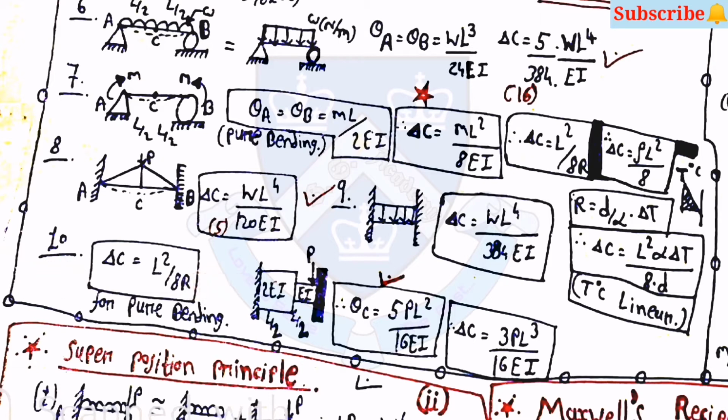Then there is the example: if two bars are connected face to face and the rigidities are 2EI and EI, then theta C is equal to 5 into PL square upon 60 EI and delta C is equal to 3PL cube upon 60 into EI.